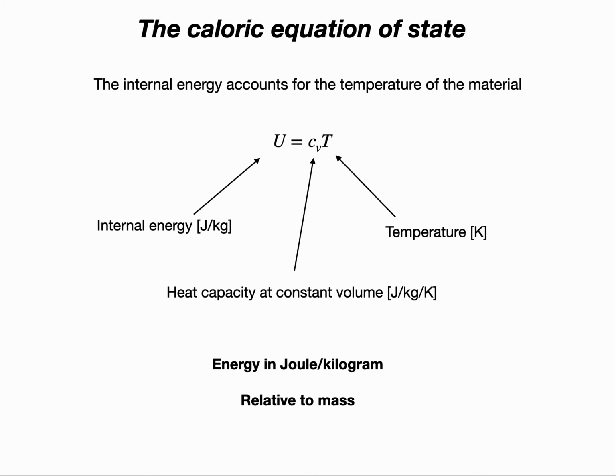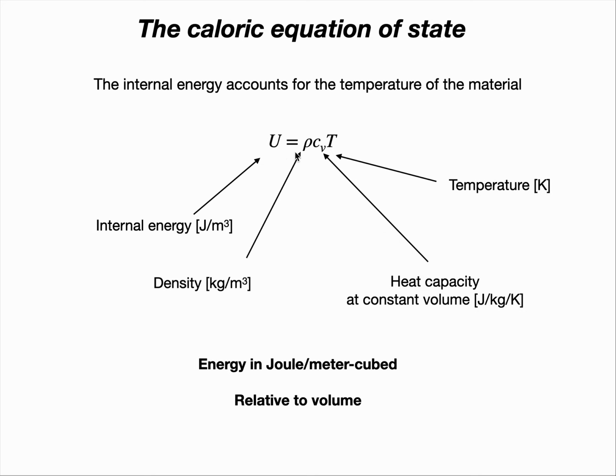If we define now the energy this way, notice the appearance of density now in front. This is a different way to define the internal energy. It's a way to define the internal energy in unit joule per meter cube. And in that way, the energy is relative to the volume of material. So it's again a definition of internal energy, but it has a different unit. So be always very careful to what you're looking at.